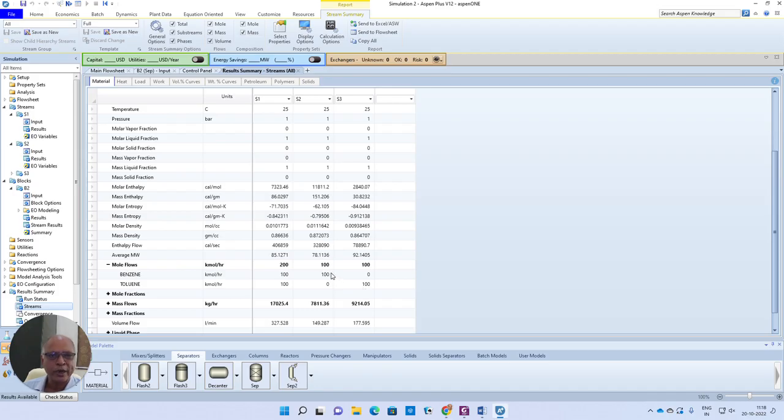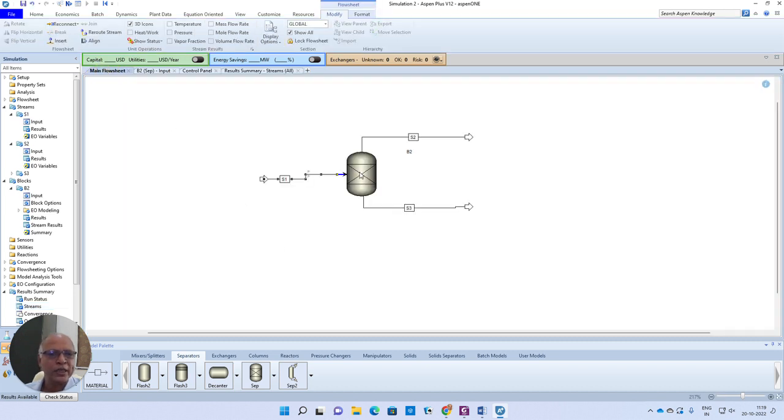Do you think 100% separation is possible by any mass transfer operation? Probably to some extent you will be able to achieve 100% separation through phase change, not by absorption, not by distillation or any other. Right? As you go nearer to that 100% separation, the driving forces become very small, very small or infinitesimal. So the time required, the size of the equipment will be unmanageable. So you have to be very reasonable while specifying this kind of separations, right?